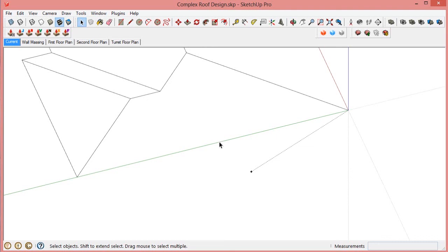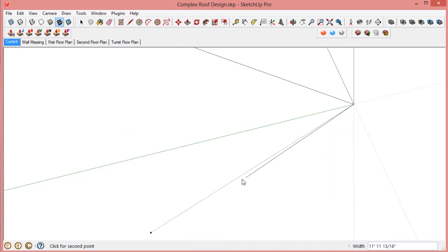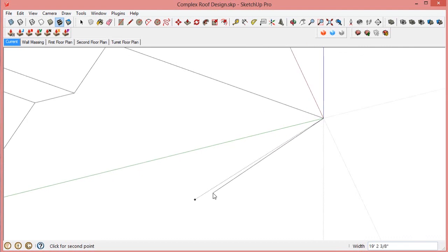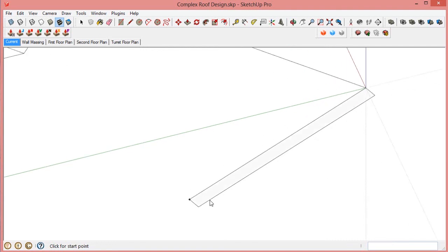The R shortcut key was originally designated for the standard rectangle tool, and I have reassigned it to the rotated rectangle tool for my setup, because I find the rotated rectangle tool to be much more useful than the standard tool. So I'm typing R for the rotated rectangle tool, and then it will snap in any direction, and then I click on the left mouse key to accept the length, and then click again.